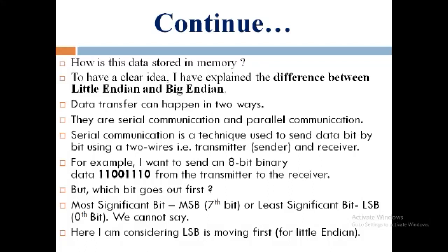Most significant bit MSB, 7th bit, or least significant bit LSB, 0th bit. We cannot determine or say that the MSB bit goes first or the LSB bit goes first in the serial communication of data transmission. Here I am considering LSB is moving first for little endian.